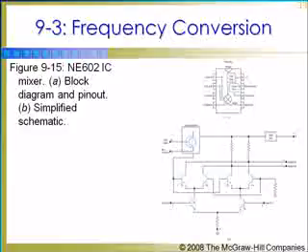The collectors are cross-connected. For example, the collector of Q1 is connected to the collector of Q4 instead of Q3, as would be the case for a parallel connection, and the collector of Q2 is connected to the collector of Q3. This connection results in a circuit that is like a balanced modulator, in that the internal oscillator signal and the input signal are suppressed, leaving only the sum and difference signals in the output. The output may be balanced or single-ended, as required. A filter or tuned circuit must be connected to the output to select the desired sum or difference signal.